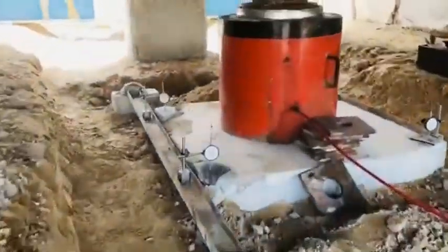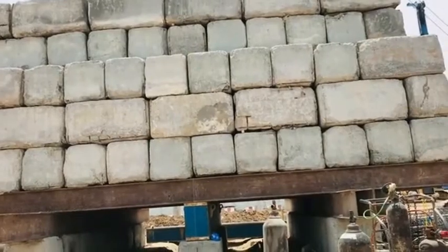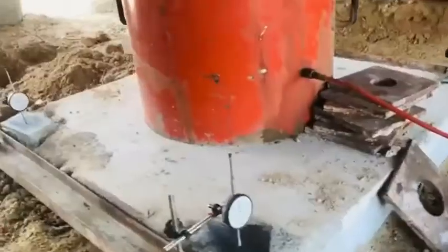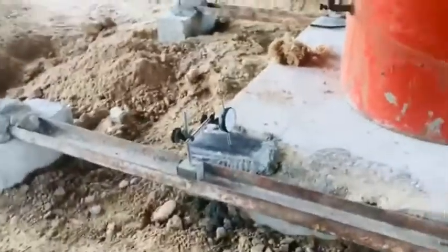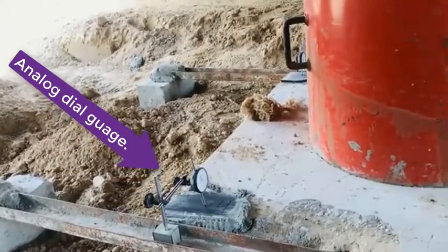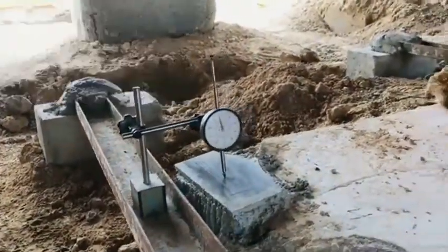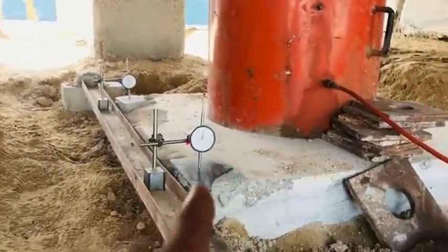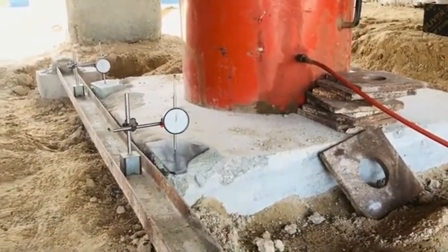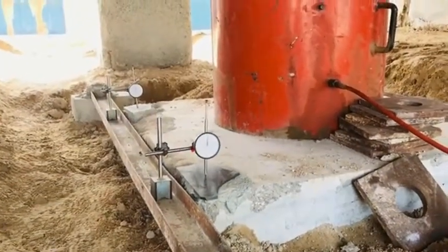A hydraulic jack will be placed on the pile, and then we will load the hydraulic jack with the testing load, which will be between 150% and 200% of the design load. The vertical settlement will be measured by the dial gauges, and the values obtained will be manually recorded on paper at 15 minutes or 30 minutes interval. This value will then be used to analyze the result to determine if the pile fails or passes. It will take 24 hours to complete this test. You just keep taking the readings at 15 minutes interval until the 24 hours clocks. Some companies even continue until 26 hours to complete this test.